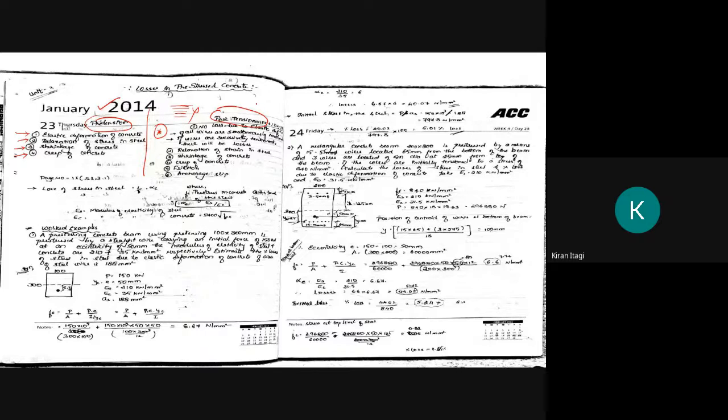If they tension the first one, then the second one, third, fourth, fifth, and go on doing it individually, there will be loss due to elastic deformation. This is the first loss. If all are tensioned at a time, then there will be no losses in the post-tension.